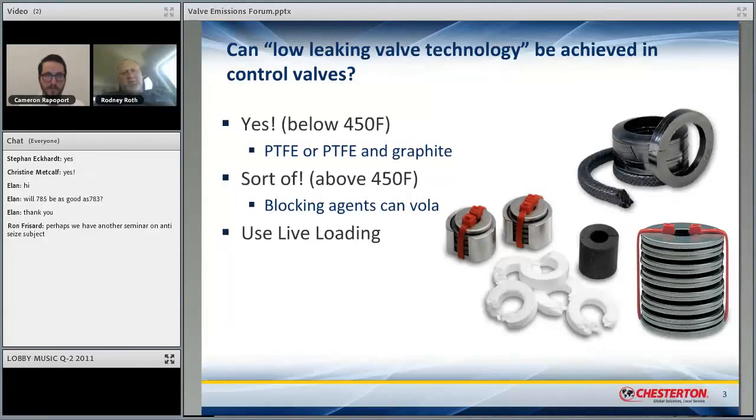It's radiant heat that goes from the bottom portion of the valve and radiates up through the valve into the stuffing box. Additionally, depending on the process, some materials are very good at heating stuff up, and some of them are very bad at carrying heat. So if you've got a Dowtherm product, which is a heating oil, it's probably going to heat the valve up very quickly and very evenly. But there are other processes, even water is one of them, that doesn't do very well, because it's going to transition to a gas itself. So we have no issues with that.